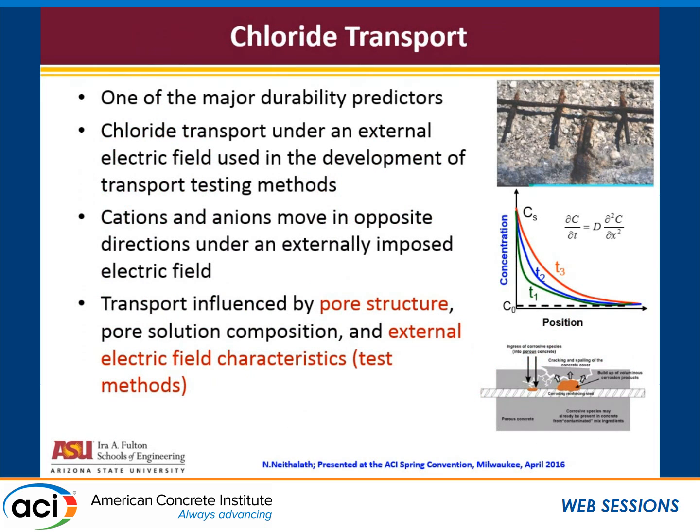Coming into chloride transport. Chloride transport, like all of you know, is one of the major durability problems. Chlorides come in and start corroding the steel. We use accelerated test methods. We don't have time to pond a slab for 2 years and find out what happens to the steel.